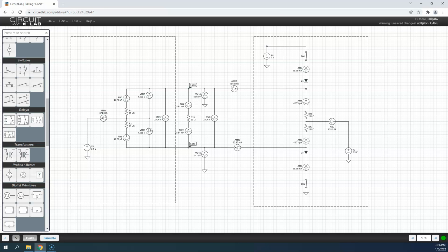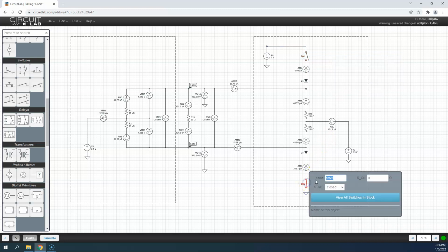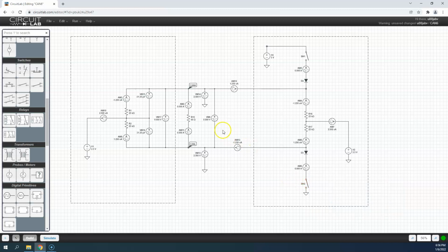Probably more confusing than it is helpful. But if you had stuck in your mind, how can I be driving this to one value and still have this 2.5 volt supply be there? This is the reason why. If you look at this long enough, hopefully it'll make sense. Once again, I'm back to some microvolts, a really small voltage, just because of the meters themselves. I'm flowing some current through the meter, so there's a voltage drop across the resistance of the meter. Because it's simulating a real meter, it shows this voltage.